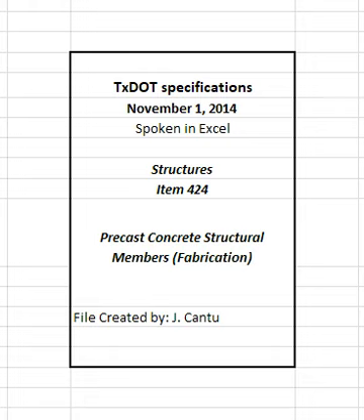Do not allow the modulus of elasticity of individual strands to vary more than 1% from each other when multiple strand tensioned. Use a weighted average modulus of elasticity of strands to calculate elongation for multiple strand tensioning operations. Establish reference marks on the strand for measuring elongation after initial tensioning. Provide means for measuring the elongation of the strand to an accuracy of 1% of the theoretical elongation or 1/8 inches, whichever is smaller. Establish independent references on the strand adjacent to each anchorage, to indicate slippage that may occur between the time of initial stressing and final release of the strands.